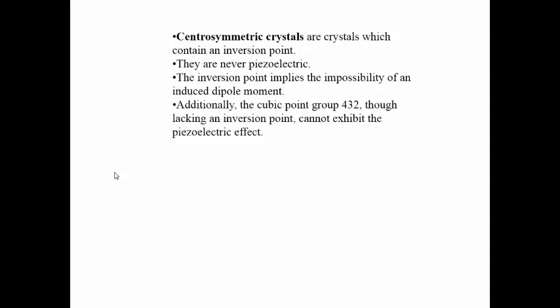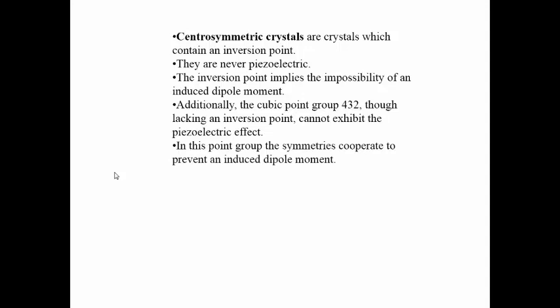So that's very exciting. Now, on the crystallographic side of the picture, centrosymmetric crystals are crystals which contain an inversion point. They are never, never, never, never piezoelectric. The inversion point implies the impossibility of an induced dipole moment. Additionally, the cubic point group 432, though lacking an inversion point, cannot exhibit the piezoelectric effect because the symmetries in that point group cooperate to prevent an induced dipole moment. Very interesting proof, which I'll show you some other time.